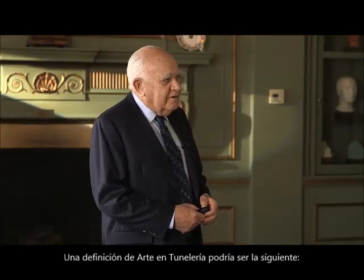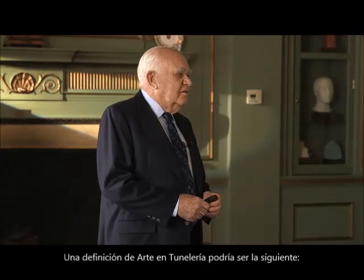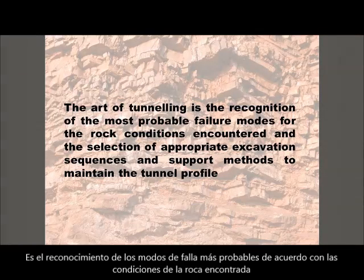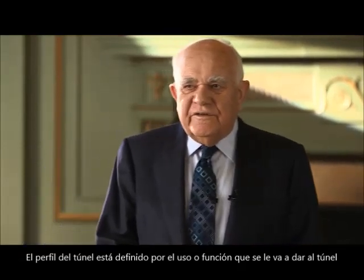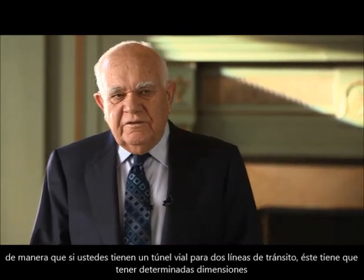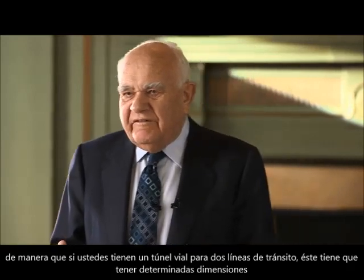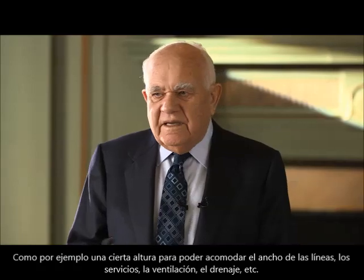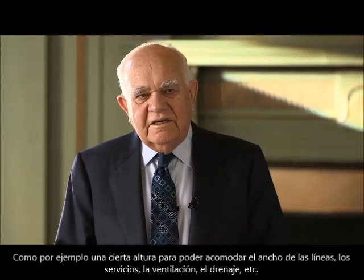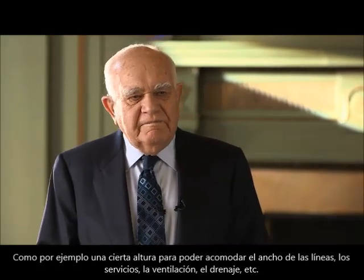A definition of the art of tunneling might be this: it is the recognition of the most probable failure modes for the rock conditions encountered and the selection of appropriate excavation sequences and support methods to maintain the tunnel profile. The tunnel profile is fixed by the function of the tunnel, so that if you have a highway tunnel for 2 lanes of traffic, it has to have certain dimensions, certain height, in order to accommodate the lane width, the services, the ventilation, the drainage, and so on.